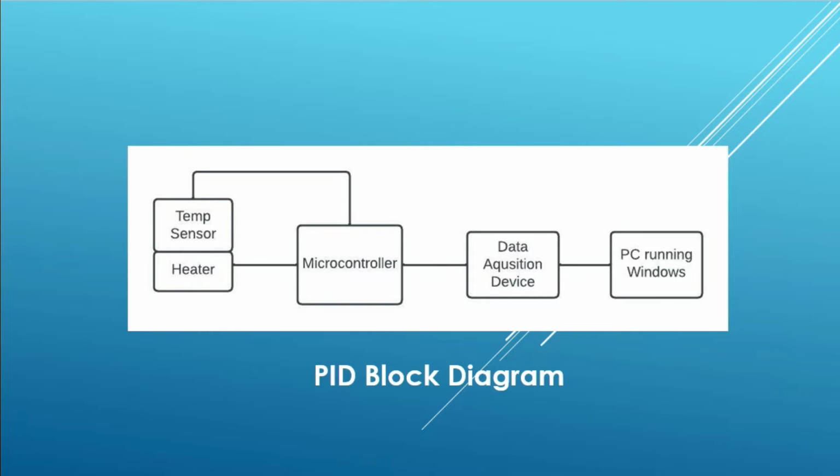The current temperature and the set point temperature are then plotted on a PC. This allows us to look at the heater's response to the PID control loop. It also allows us to tune the PID loop by dynamically changing the proportional, integral, and derivative constants to optimize the operation of the loop.